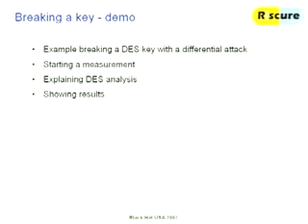So what the tool does, it first programs the key in the card, and then it just runs over sending random data, triggering the measurement, getting the measurement out, and then also getting the random, encrypted reply back, and storing that with the trace. So every measurement has its own input and output data, so that we can then use it for the correlation attack. So, well, this will be measuring for 2 or 3 minutes, so I quickly go back to explain to you this attack.